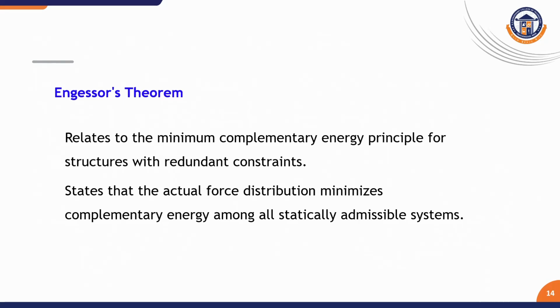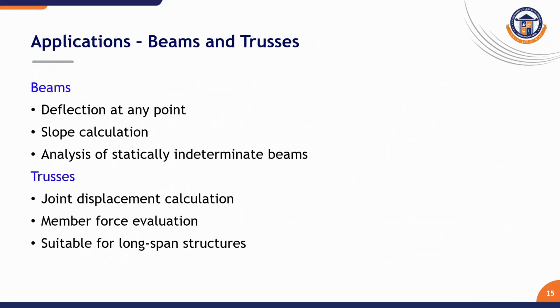Engesser's theorem. Engesser's theorem is based on the minimum complementary energy. It states that among all the statically admissible force systems, the actual system minimizes the complementary energy. This theorem is mainly used in indeterminate structures and redundancy analysis.